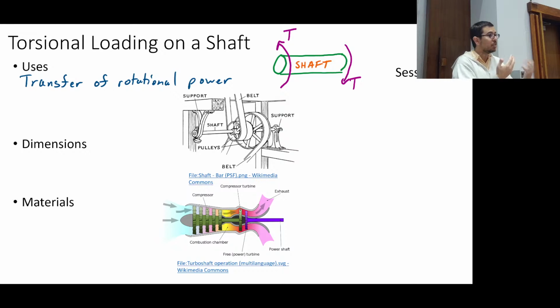And there's going to be a reaction force on that wheel, and so there's going to be a load in between the sprocket. There's going to be a torsional load. The sprocket's going to want to go one way. The wheel's going to want to go the other way. And so that torsional load is going through the shaft that's connecting the sprocket to my axle.